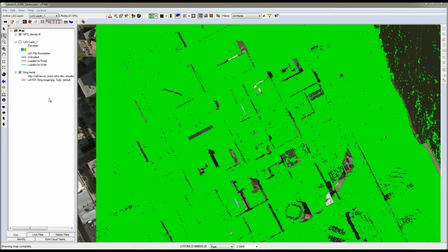So at this point, as the person responsible for this preliminary QA/QC, you would need to decide if it would be appropriate to go back and either change some of the settings to create your point density images, in the case of the scan angle, if it would be appropriate to adjust that, or whether there are some other acceptable physical reasons for there being some voids in the data.